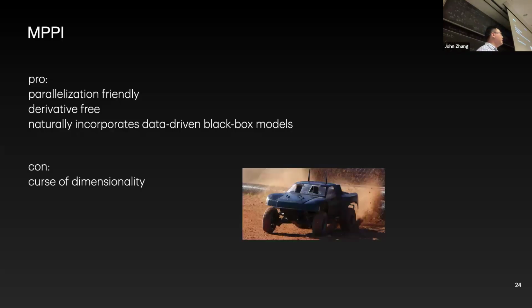In the last 5 to 10 years, the most successful application for MPPI has been off-road autonomous driving, where MPPI is basically the standard. If you talk to folks at CMU working on autonomous driving in Basti's lab, and some other groups, MPPI is the stock controller, because in the off-road case you have a relatively small number of control dimensions.